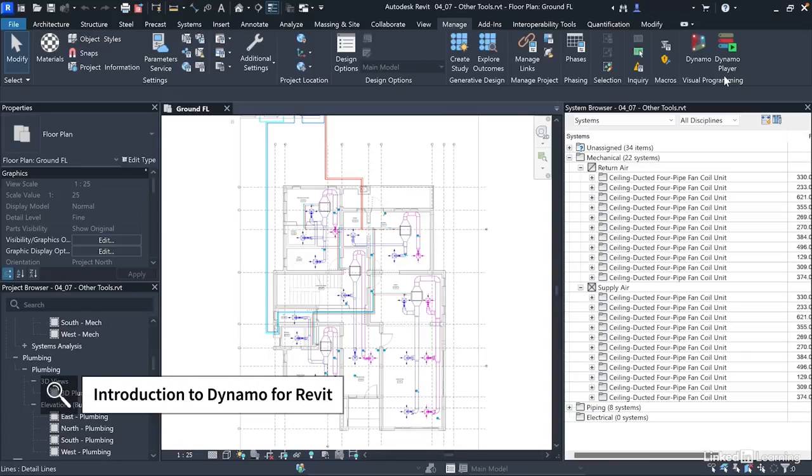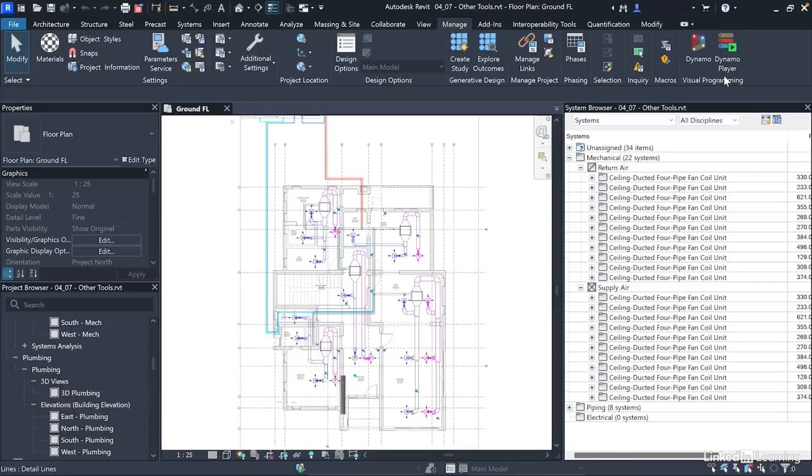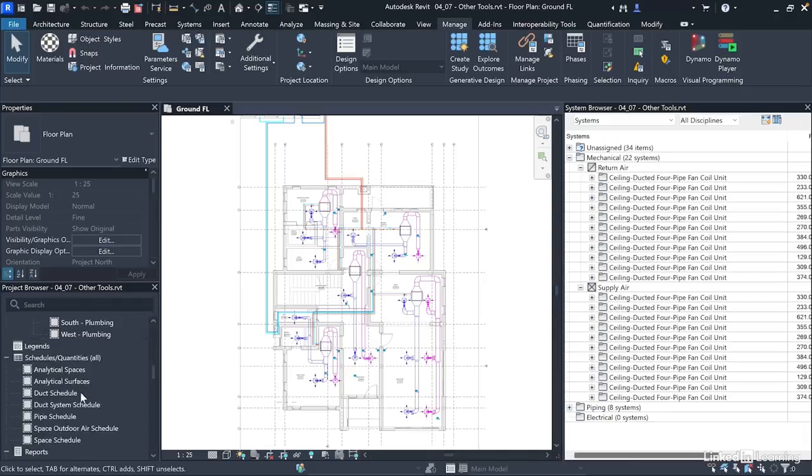Obin. But sometimes you want to perform design and engineering tasks with specialist tools like Carrier's Hourly Analysis Program, Trane Trace, or countless other tools built on DOE-2 or EnergyPlus simulation engines. Revit can provide the raw data you need, perhaps as a CSV file or in gbXML format. For example, we can export some of the schedules we generated earlier.